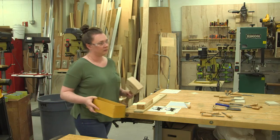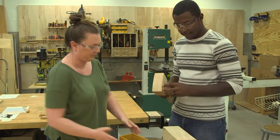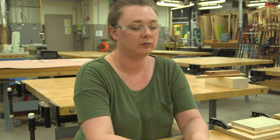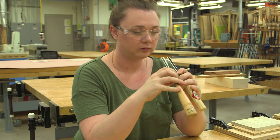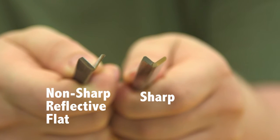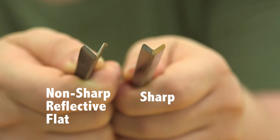Once you've determined which hand carving tools you need for your project, find a shop staff person to check out the specific tools. Before you begin carving, you need to check your tools for sharpness. It is imperative that your tools are razor sharp so that you get a clean, smooth cut. The cutting edge of the tool should be razor thin. A sharp edge does not reflect light.